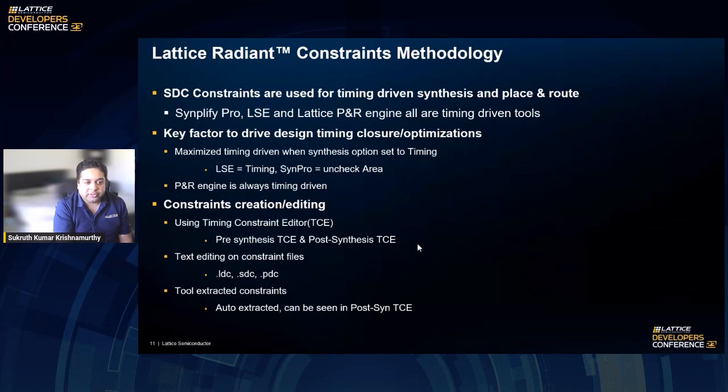Along with that, users are also provided with a source editor to create constraints in the form of a .ldc file that can be used by the LSE tool, a .sdc file that can be used by both LSE and Synplify Pro, and a .pdc file that is used for map and par. In certain cases, the timing tool also generates auto-extracted constraints whenever a PLL or an oscillator is used. These auto-extracted constraints can also be seen in the post-synthesis timing constraint file and are also written in the UDB file, or the Unified Database file.